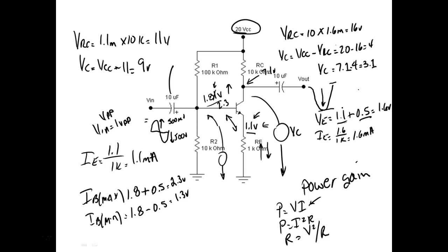Now, what happens, guys, is that we're taking our output across the transistor. So what happens on this amplifier is that if the transistor cuts on more, so if the input voltage goes up, the transistor cuts on more and the output voltage goes down. So one of the characteristics of this one is that your output voltage and your input voltage are going to be 180 degrees out of phase. We're okay so far?